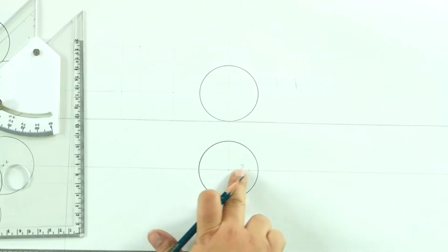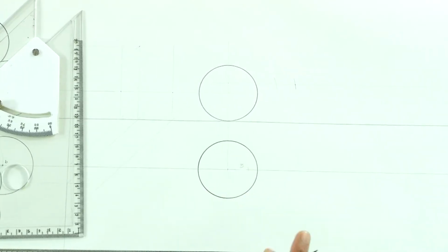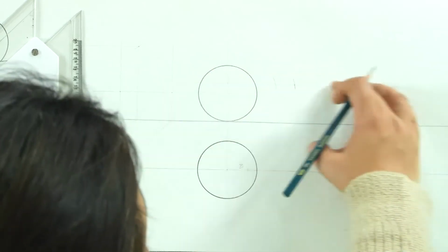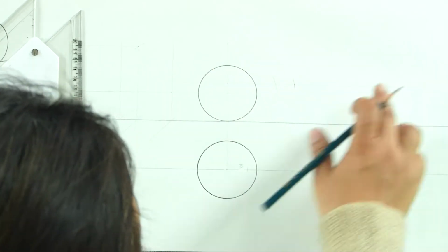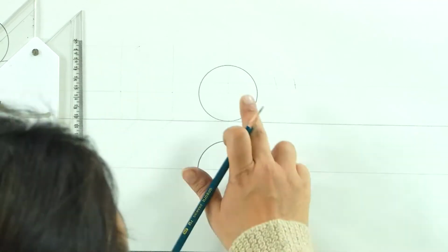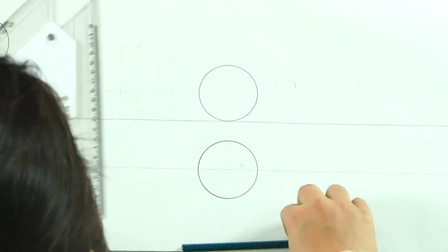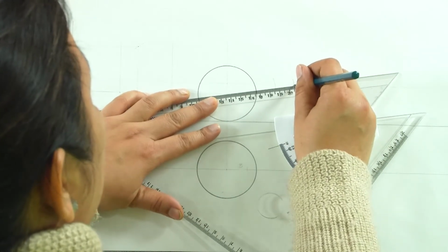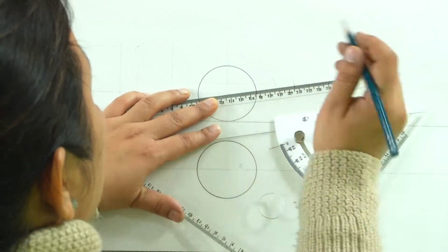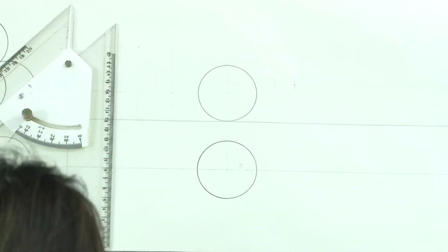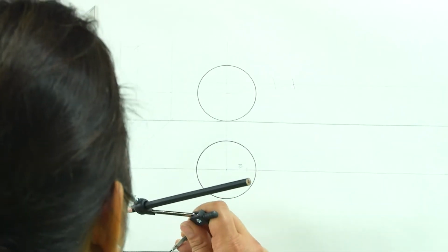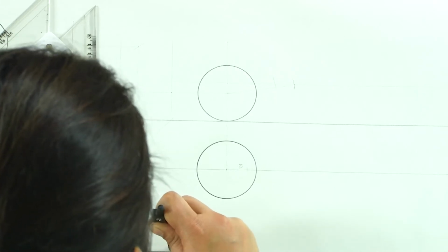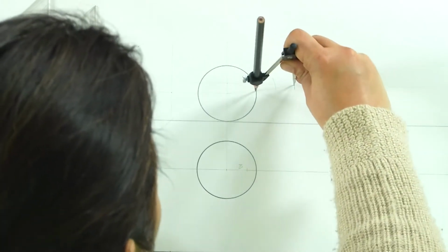and this line we assumed, the given condition is that the line joining the two centers is parallel to the VP. So, this is going to remain straight while the line joining the two centers will not be straight anymore. So, this line is making a certain angle with the HP, and now we will take the 4 centimeter in the compass with this as the center.